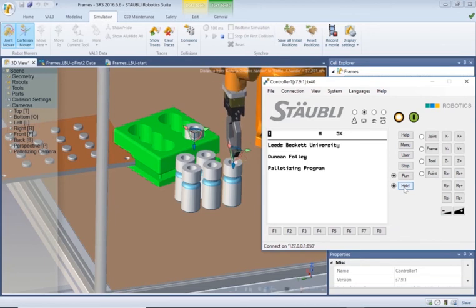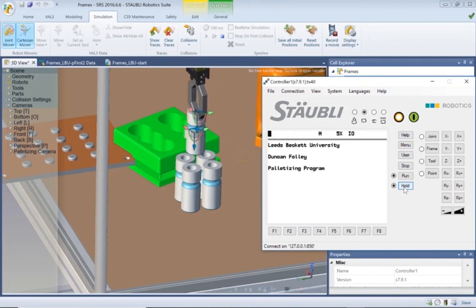You can see at the top of the right screen that grasp is possible, so it's within that. I've set the gripper device so anything within 25 millimeters that's a handle can be grabbed. It looks like it's taken the rotation of 20 degrees, and it looks as though it's working. We'll let this play out.